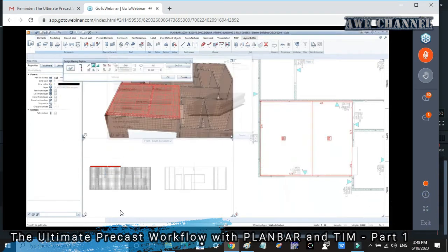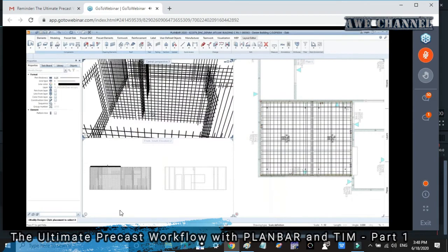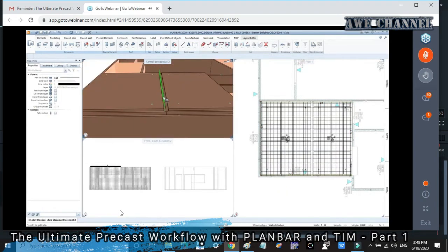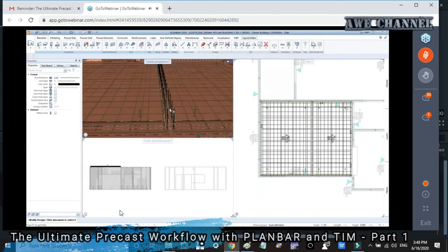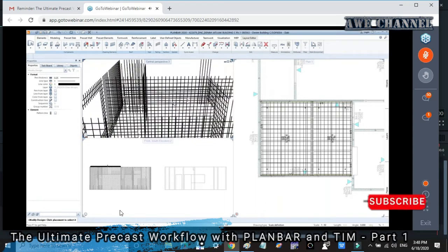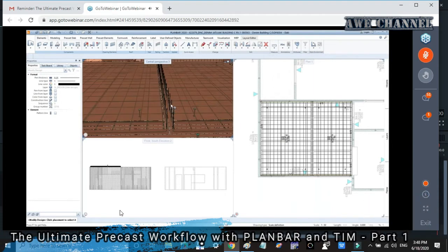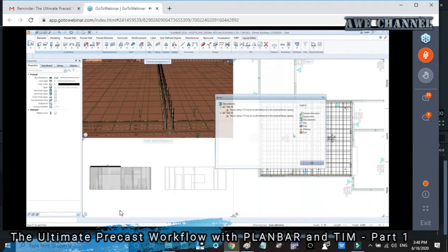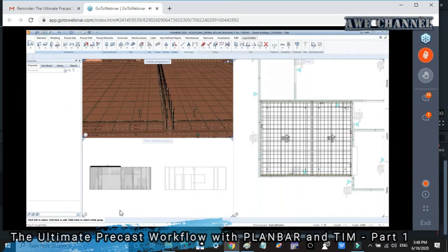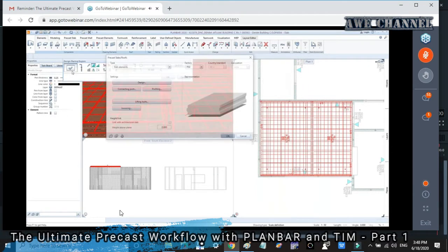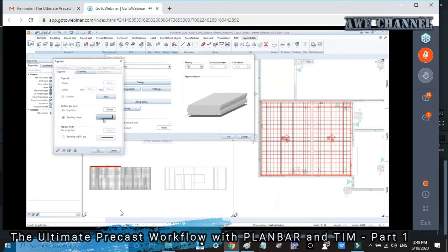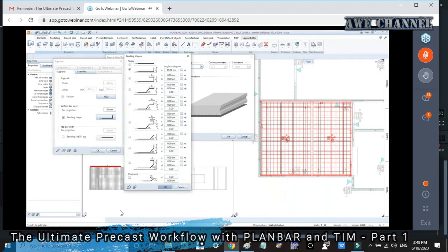And now you can see what I have when I click OK. You have bar protrusion or bar extrude from your precast wall element as a reinforcement connection. If you want to have a different shape for the connection, our solution is also available for you. You can choose which one is fine for you, but don't forget to assign a value for any bending shape. Otherwise, you will not get any result.